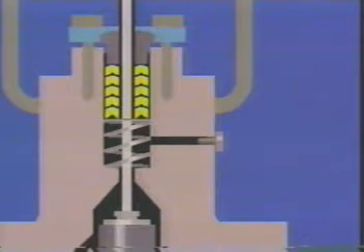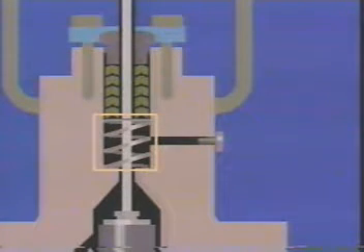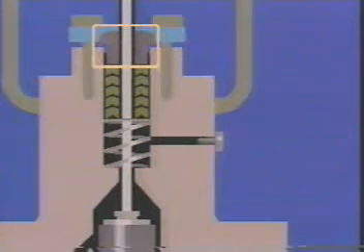A popular form of this packing is the chevron or V-ring. In addition to providing low friction, it creates an excellent seal. Because of its shape, a pressure increase in this area causes the packing to seal more tightly. In some cases, a spring is used to provide a minimum pressure against the seal. When a spring is used, the packing flange is not adjustable.